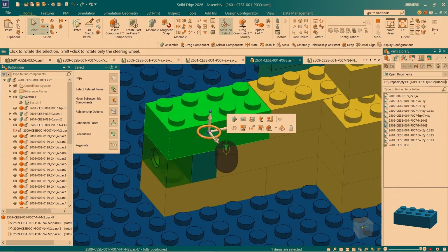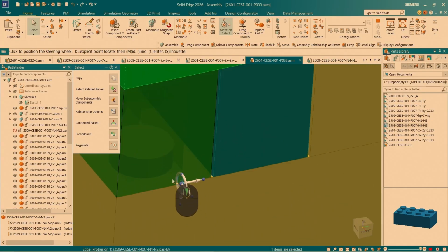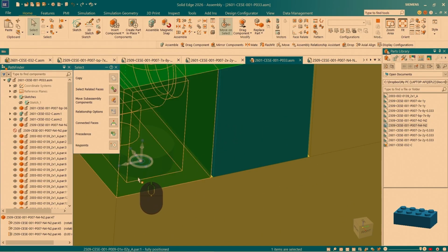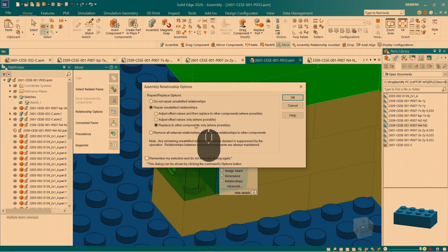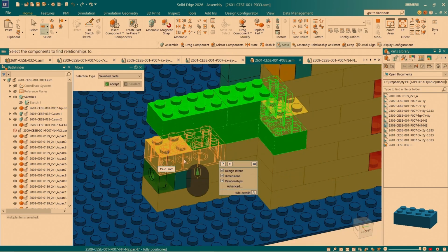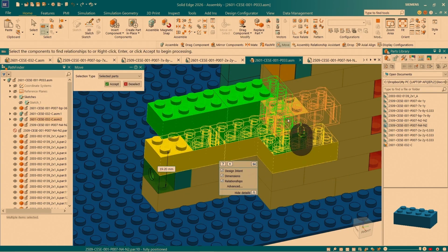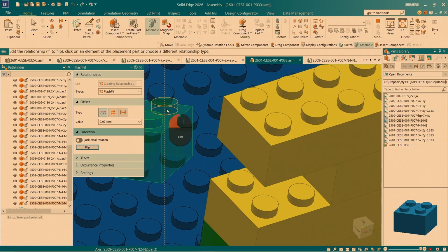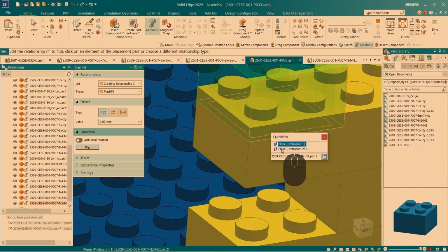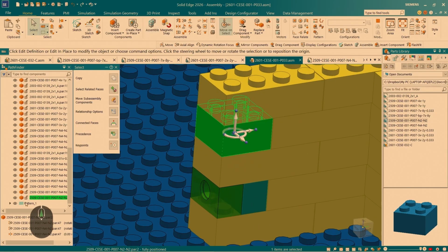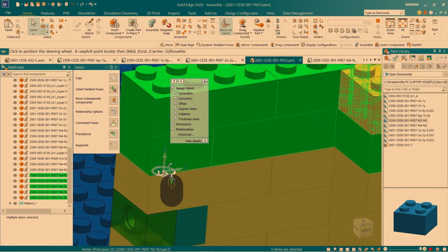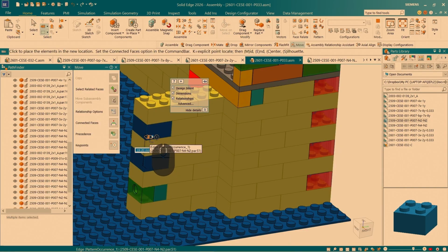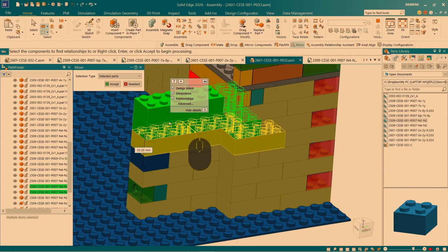We can repeat the same technique we've been using to copy 2 rows of blocks using the bottom of this peg as a base point, copying them to the bottom of this peg. We'll search for relationships with blocks below and beside the copied blocks and add a 2x2 block to fill in the gap. Once we have the 2x2 block fully constrained, we can copy 2 rows of blocks, including the 2x2 block, using the same technique, and search for relationships with the blocks below the copied parts.